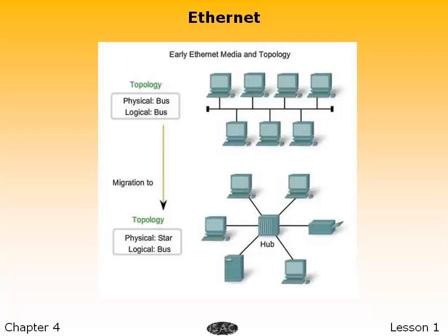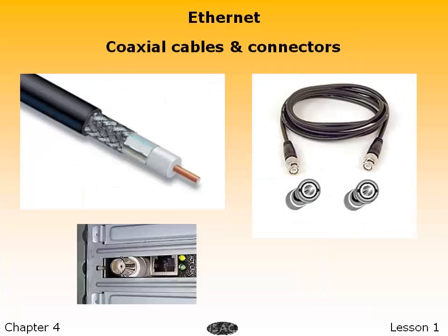In 1987, SynOptics introduced the first twisted pair Ethernet at 10 megabits per second in a star-wired cabling topology with a central hub, later called LattisNet. They evolved into 10BASE-T, which was designed for point-to-point links only, and all termination was built into the device.